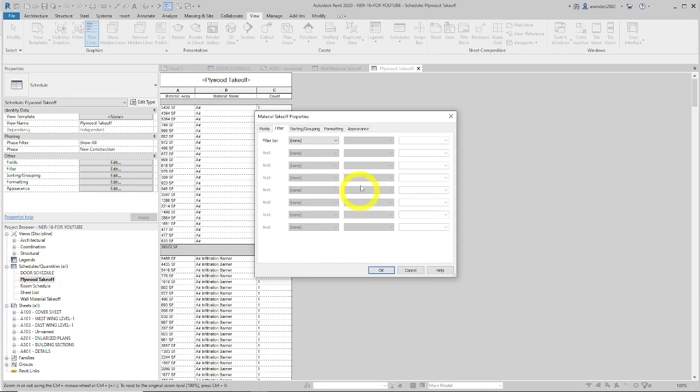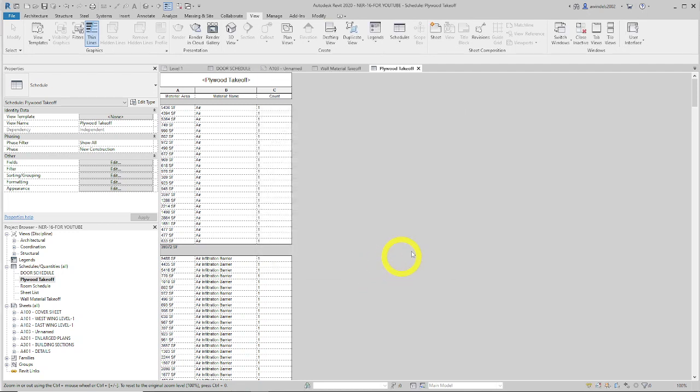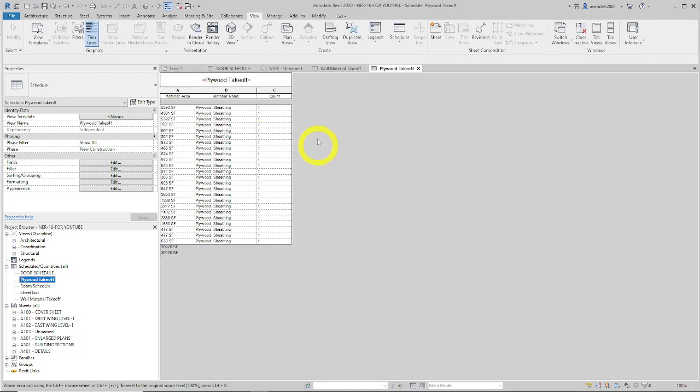And we're going to filter by material name, and we're going to select a name. I'm looking at the picture to help you out a little bit and say equals exactly this. It begins with the different Boolean operators kind of here in a way, if then statements, less than, sort of like Boolean operators. We'll go to plywood sheathing. It has to equal that, and I'm going to hit OK. That's going to modify everything. So it modified our